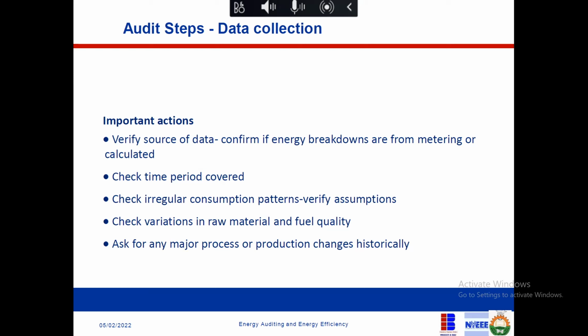There are some key important things you need to observe when you are collecting your data. Verify the source of data. Know whether the energy breakdown is coming from metering or from calculation they've done. Check the time period covered, right? Check any irregular consumption pattern. Take note of it. Then check variation in raw materials and the fuel quality. The worst is, if the fuel is bad, then most of it will go off as carbon, and so on and so forth. So there are a whole lot in here.